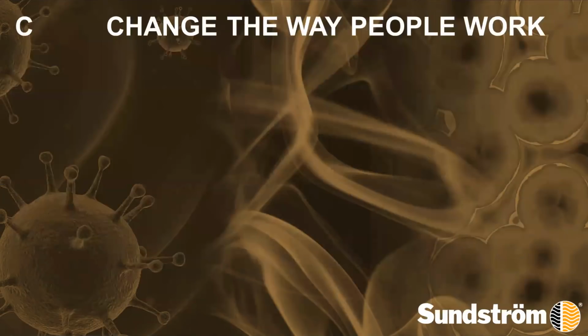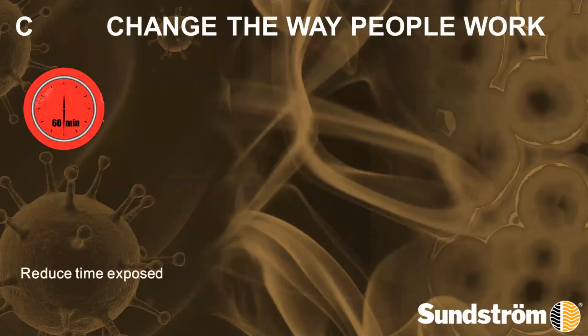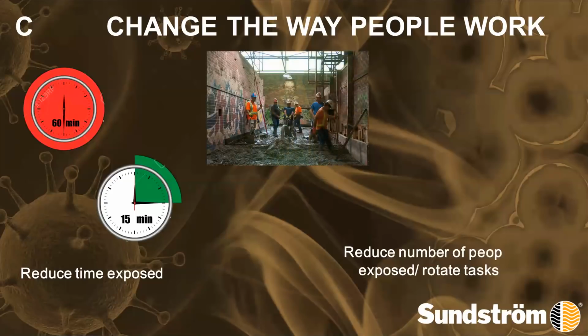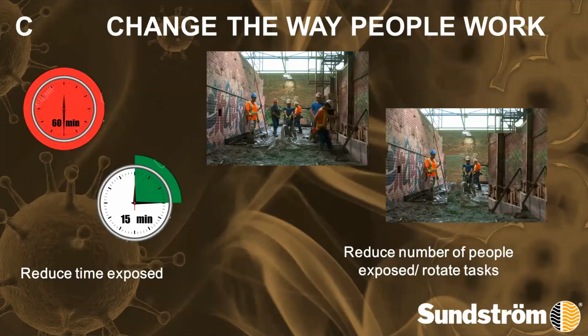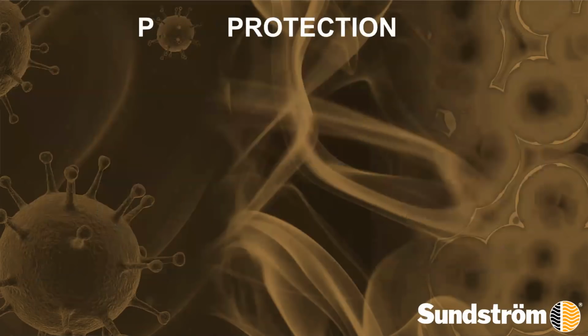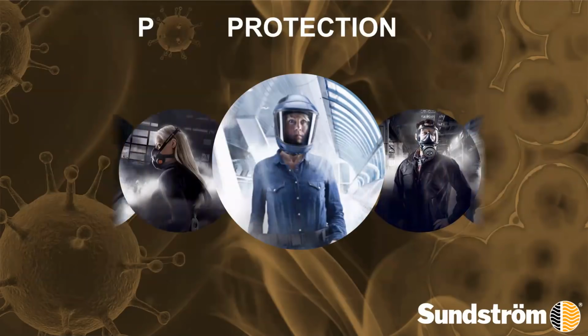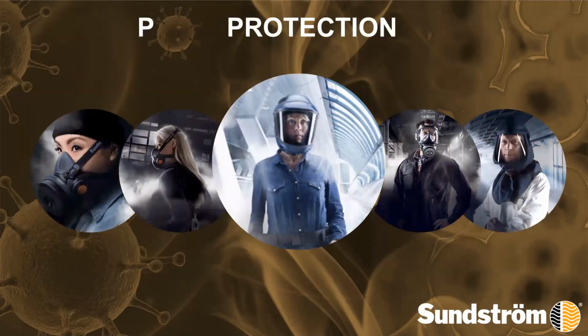The next thing you can look at doing is changing the way that people work. So that could be to reduce the time that they're exposed to the hazard. Or alternatively, we can reduce the number of people that are exposed to the hazard, or rotate people's tasks. And then finally, we get to protection. If we can't protect people up until that point, we then need to form a respiratory protective program and provide people with respiratory protective equipment.